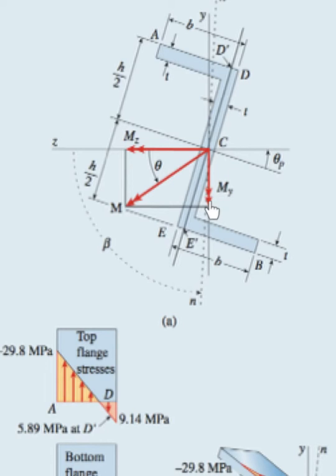Now let's look at this component and see whether it causes compressive stresses there or tensile stresses. Imagine again that your thumb is facing the direction of these arrows. Look at where your four fingers are going. Are they going into the page of this side of the y-axis or this side of the y-axis? You'll notice that your four fingers are going into this side of the y-axis.